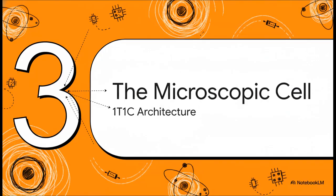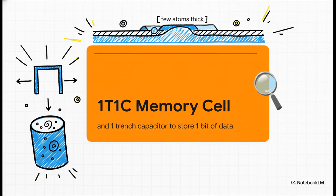Section 3, the microscopic memory cell. Let's zoom in to the absolute smallest unit of this array, the 1T1C architecture. This is a foundational concept. What is 1T1C? Mark this as a short note question. It stands for one transistor, one capacitor. The transistor is basically a logic gate to access data, and the deep trench capacitor is a microscopic bucket that stores one bit of data as an electrical charge. The insulator trapping those electrons is literally just a few atoms thick.